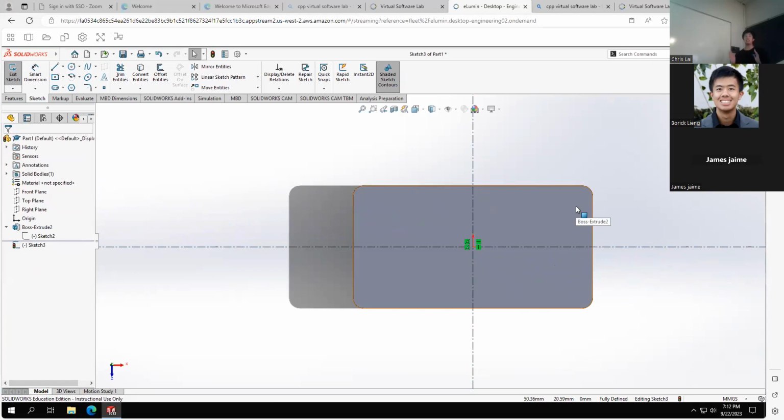Another good practice, or another thing you can do to make less work for yourself, is that if you know your sketch is going to be symmetric before even making it, you can think about where it's symmetric about, right? So you can draw part of it, and then you just start mirroring it across the axes or the lines, which is why I have my infinite construction line right here. Because I'm going to be making a cut onto the cake on the top right here, I know that it's going to be completely symmetric vertically.